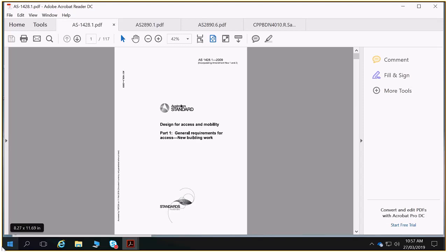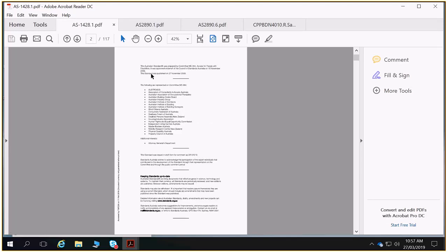Once you know all those things, you go, okay, we need X many car parks, X many need to be disabled, and so on. But as an absolute bare minimum, because we're supplying a unit for a disabled person, we have to supply at least one disabled car park as a bare minimum by the client's requirements. So we look at what the council requires, and then we both.